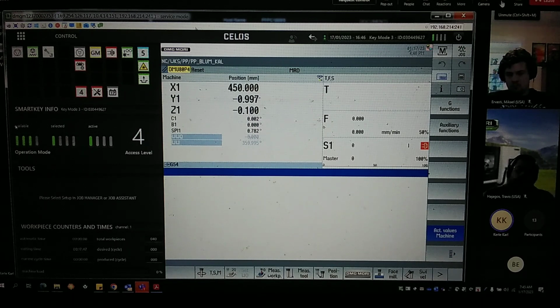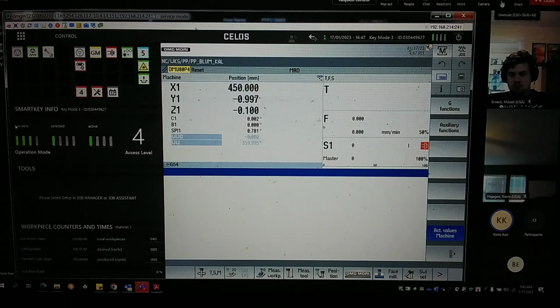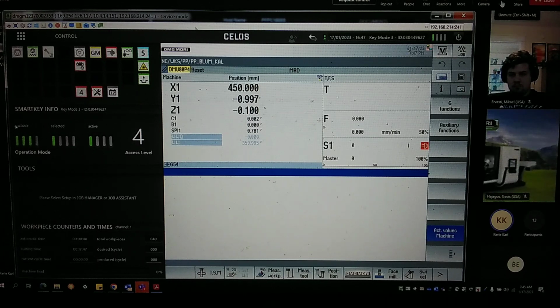Operating mode 3 means automatic program run, but independent, it's active. Also, when you press the full sequence button in that operating mode, a program will be worked off only block by block. Every block you have to start separately. Continuing, you have to keep pressing the confirm button in that range of automatic program run.